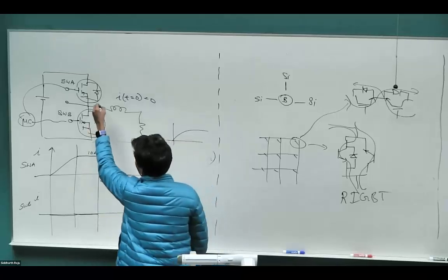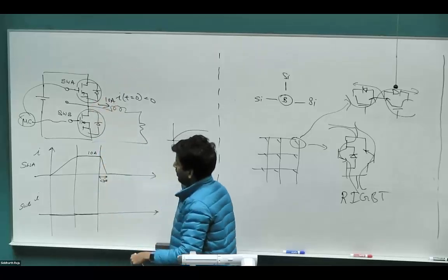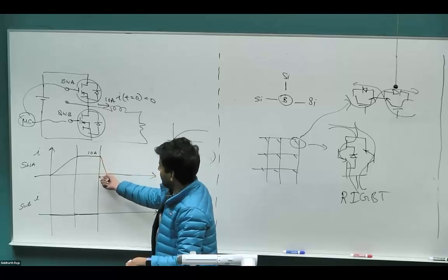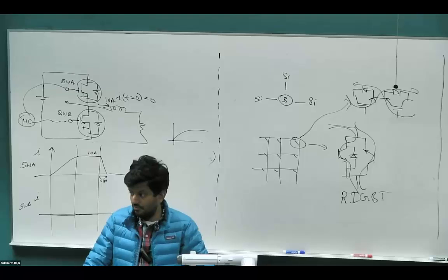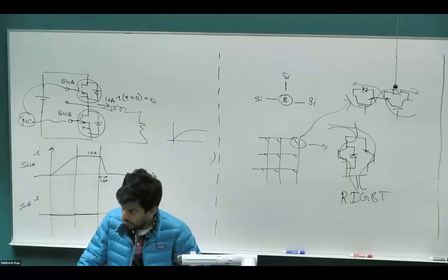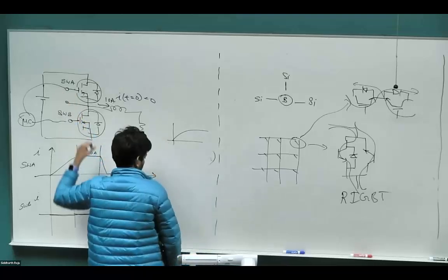So the current is going to take a little bit of time to go to 0. In that time, the inductor current was previously 10 ampere, right? So as this current goes to 0, what happens to the other portion of the current? What is the pathway for it? Yes, it's going through the body diode of switch B. Perfect. So we haven't turned the switch on yet. So this switch is the one that's on.